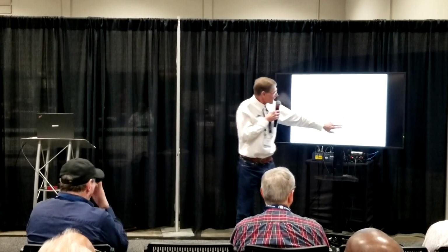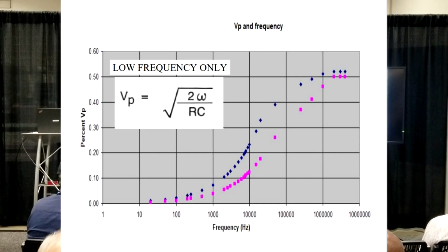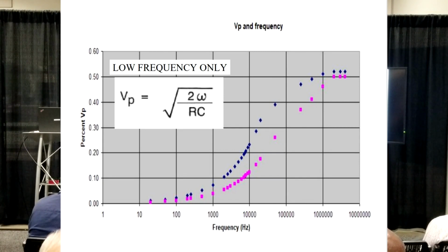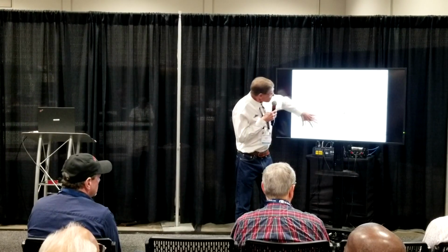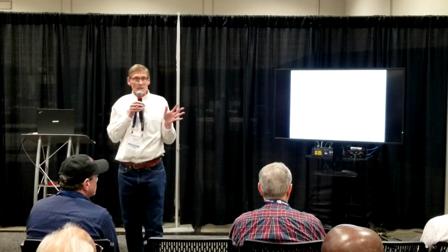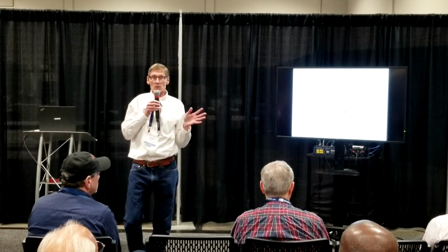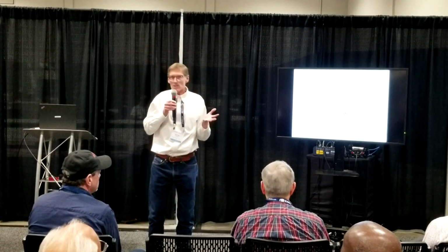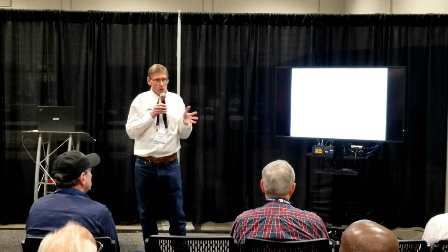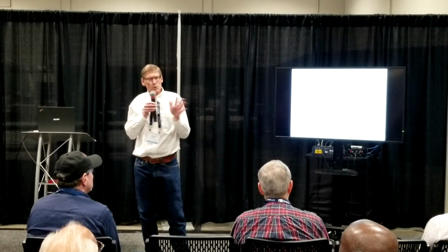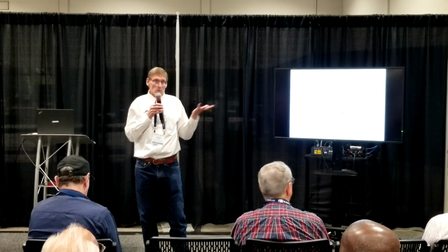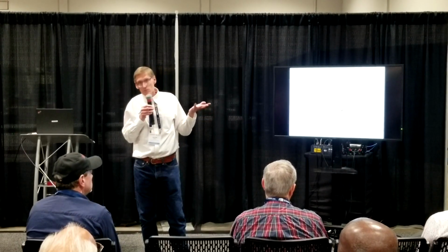This cable is actually a better design than this one. Why? Because of the velocity of propagation through the audio range, here's 10,000 hertz. We'd like the speed of our signal at all frequencies to be exactly the same. It's not. But the physics of how this works won't let us send signals down the cable at all frequencies exactly the same. That's called group delay, okay?